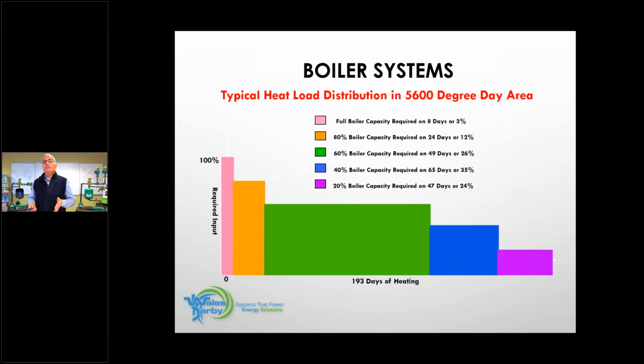So doing this heat loss today was important because it shows you how to properly size the boiler. And even if I was doing a boiler replacement, I'm still going through this exercise.